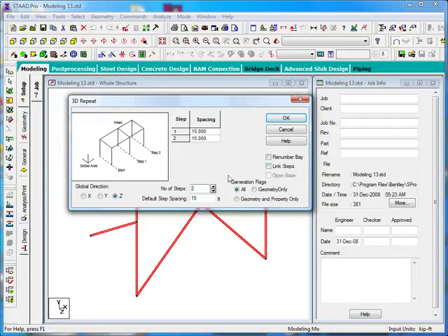If I move over to the generation flags category in the lower right hand corner, this gives us some options for exactly what we do and don't bring along as STAAD.Pro generates these multiple copies. There's a good table in the training manual that describes these different options in detail. For our purposes in this exercise, I'll just leave it set to the option to copy or generate all.